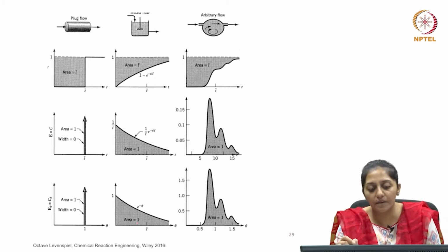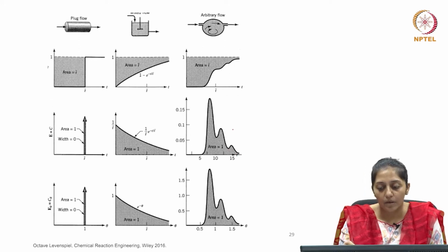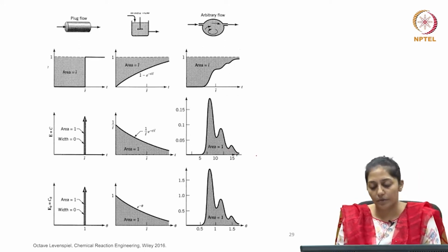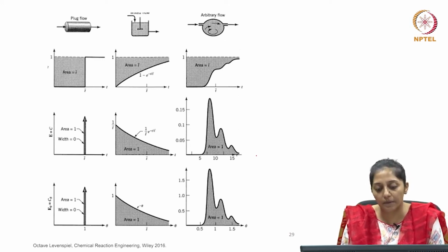If it is an arbitrary flow, then what you observe may not be an exponential increase, but can be with many peaks. Similarly, for a unit impulse input at the exit for an arbitrary flow, you may observe a lag as shown in the picture here, and subsequent peaks of decreased amplitude coming out from the reactor, where the total area can be 1.